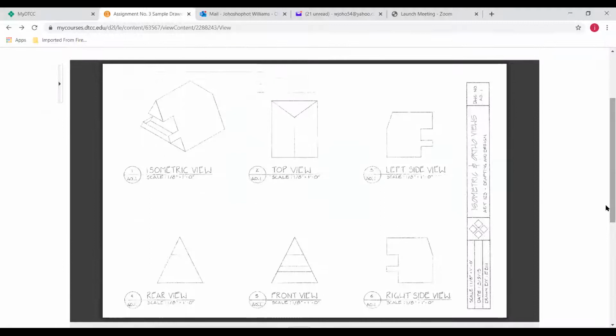This brings us back to the sample drawing. I just want to review some things. We know that the front view, so of course you have to decide initially what side of your building represents the front view. Because orthographically, we're going to place the front view in this area here. And just to reiterate, we're going to establish a horizontal plane, and that horizontal plane is going to be the same plane used for the right side and the rear view as well.